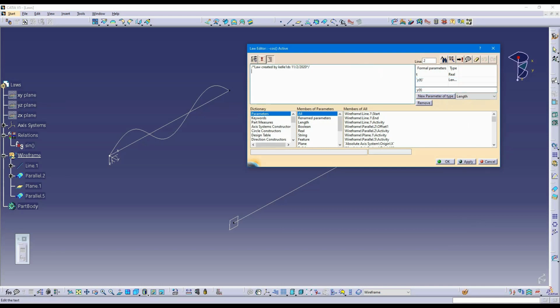So over here, work it the same way. Y of t, that's a length value, so the output is expecting to be a length value. I can do negative because it's a negative cosine curve: negative cosine, 10 millimeters times cosine, and I'm doing 2 revolutions, so that's going to be 4 times pi. 2 pi is 1 revolution, so that's really 2 times 2 pi.